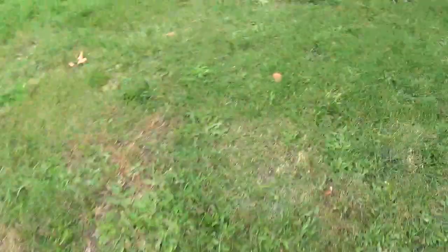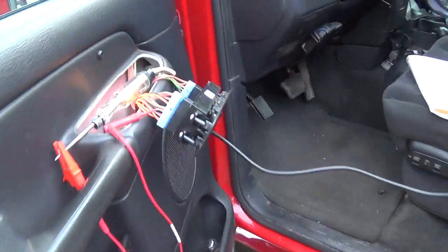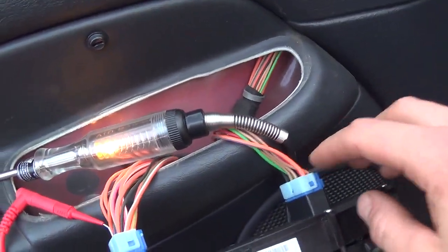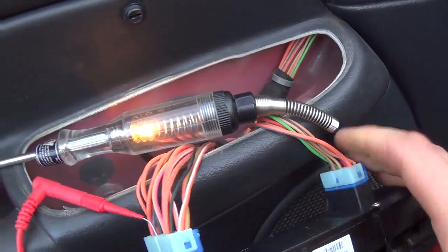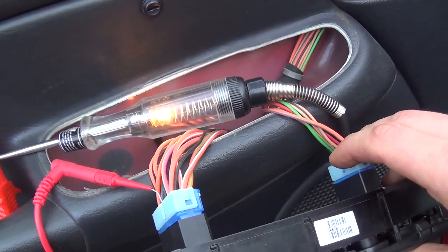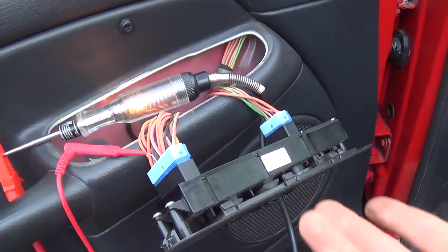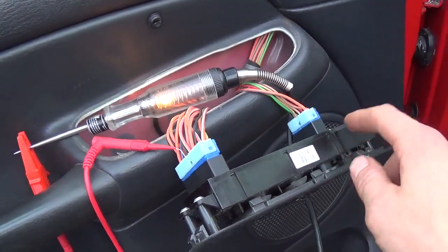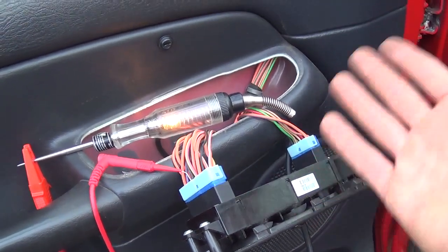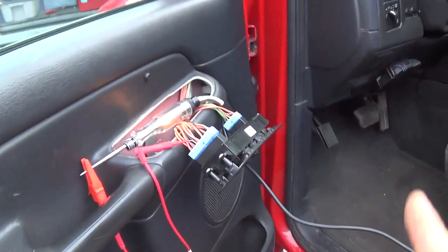Sweet. So all our problems, well, two problems: that broken wire, and something in this module that's preventing a good contact. And there it is right there. So at this point, we might take that connector off and see what's going on. But otherwise, if that wire and pin are good, it's going to be internal. And then we can always take it apart, see if there's something burned up, clean it up, whatever. But at this point, the diagnosis is complete.